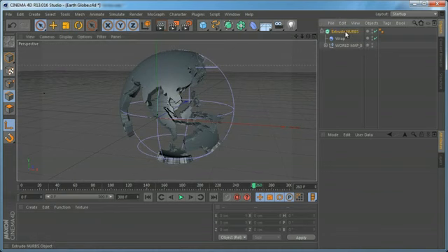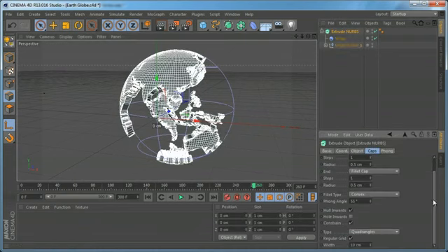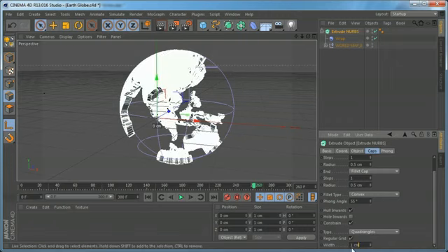But of course we need to change some settings here. Set this to 1, and this will make the mesh very dense, and it is going to generate lots of polygons, but that's only if you want very smooth results. For the sake of the tutorial, I'm going to set this to 4, but for my final render for the preview I used 1.